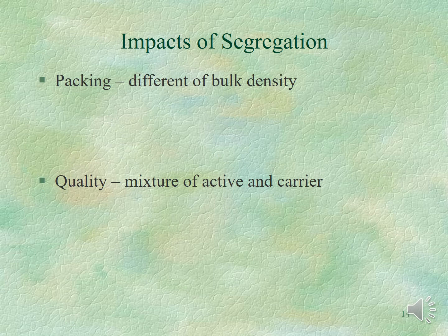Okay. So if I have a segregated mixture, it will have an impact on the packing, which will give me a different bulk density, because I will not get the same weight for the same volume because of segregation.